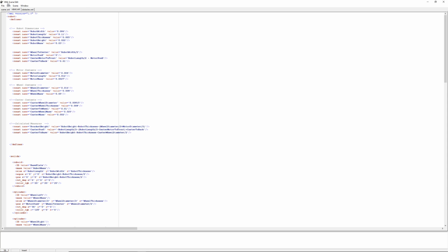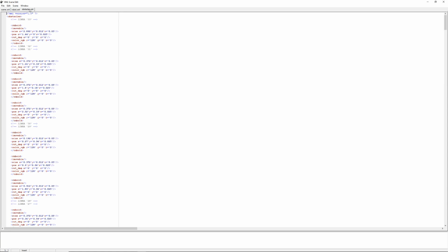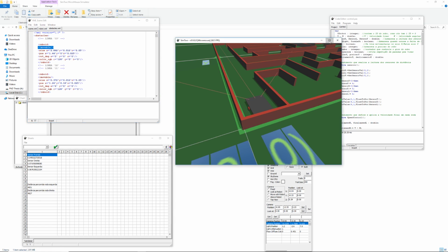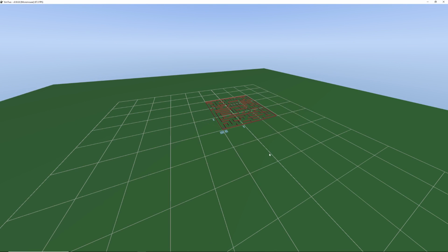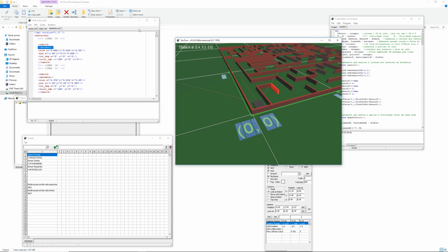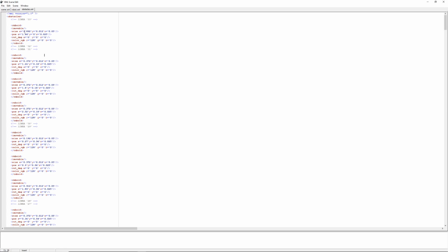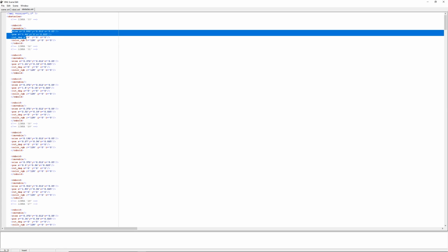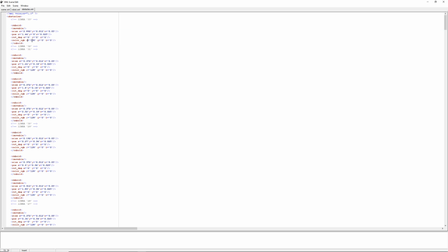The last tab you're gonna see in the XML scene editor is the obstacle XML. So basically the XML, they're cuboids, and those cuboids, they are not movable, they're fixed, because they are the walls of your maze. This is the XML that controls our maze right here. Based on the complexity, we can create more complex or simpler mazes, we can add walls, we can delete walls based on our XML code for the obstacles. And you can see that we have size, position, rotation degree, and a color. You can see they are red.